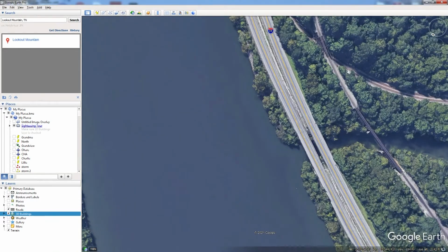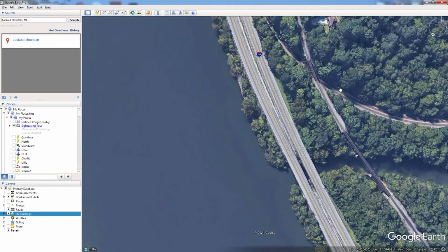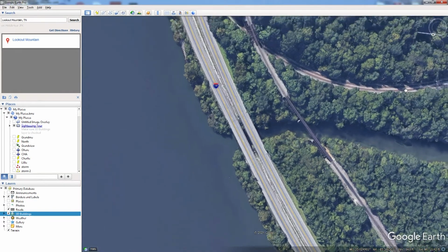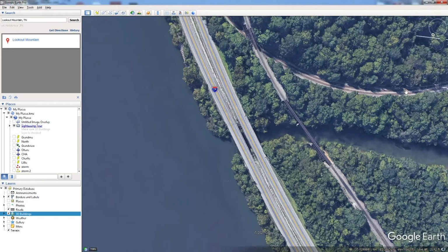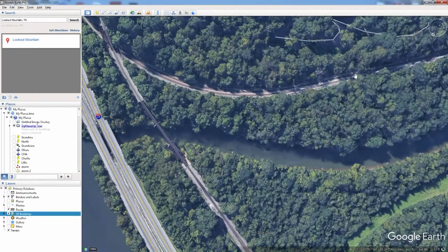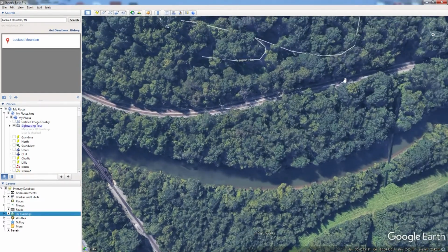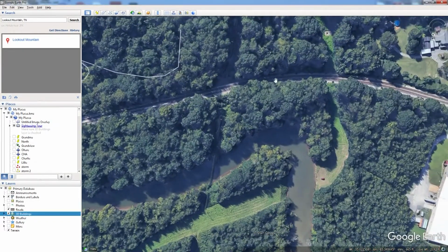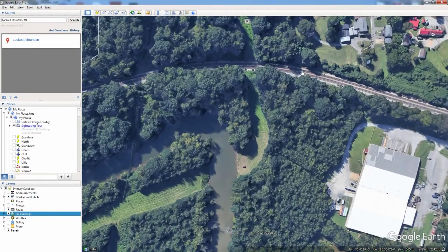In this cut, we may not get a very accurate measurement. So we'll come outside of that. It's not going to change dramatically over a short distance. So we're down to 663 here. Looks like we're on a bit of a descending grade from 665. Now we're back to 665, 666 again.